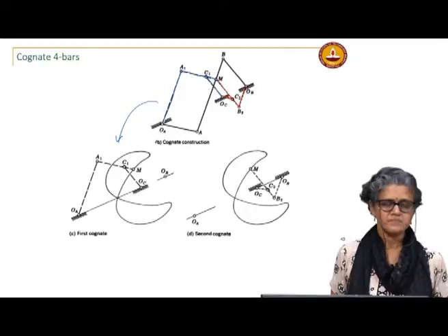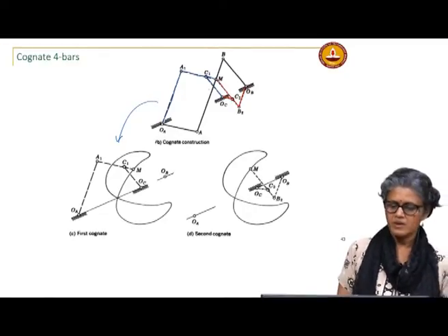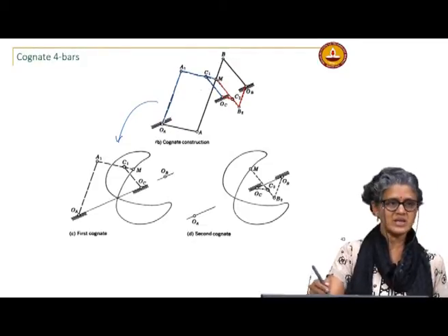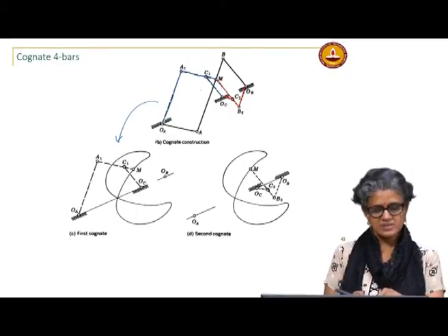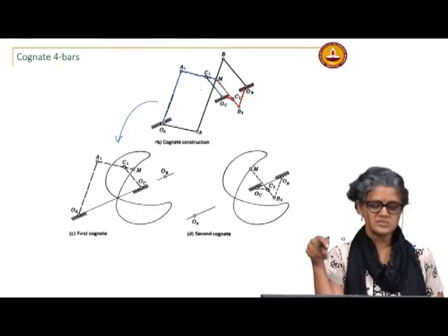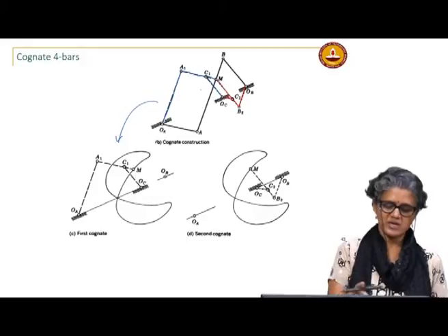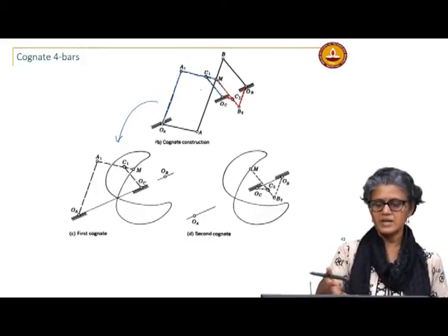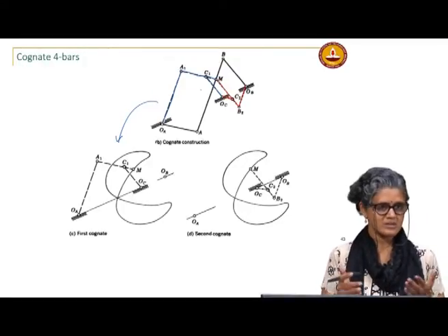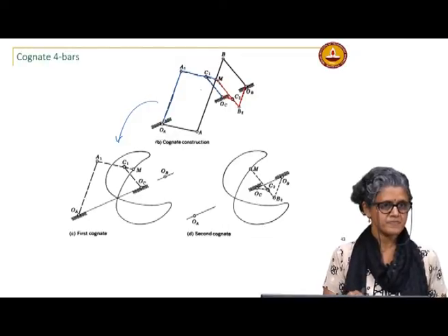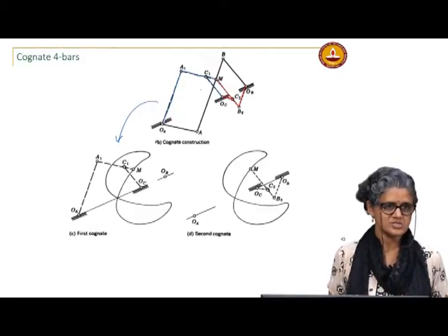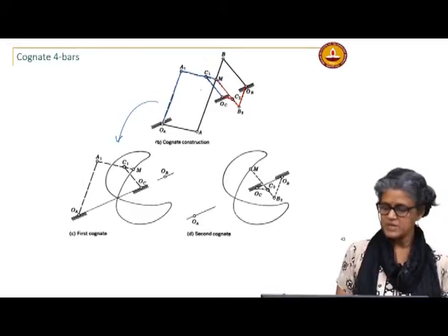Roberts-Chebyshev theorem. Okay. And so, in your original coupler, the point was actually between A and B, but in your two coordinates it can be located outside of the coupler base that you get, that does not matter. Similarly, you can find coordinates, if I give you this linkage, it will give you these two as your coordinates. So, I can construct the coordinates using whatever I want as my original linkage. I will get the same set of three linkages, okay, no matter which one I start from.